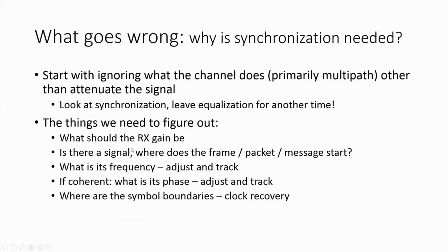Ignoring channel equalization, you have to make sure you have the right gain. You have to know when the signal occurs and when does it start. You have to adjust its frequency. You have to adjust its phase. And you have to find out where the correct symbol boundaries are. And then all those things may move in time, so you have to track them. Not only adjust, but track them.